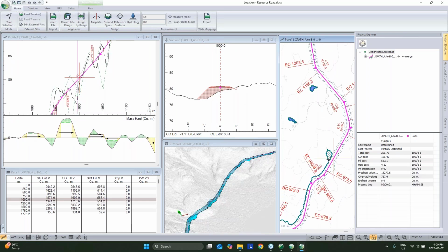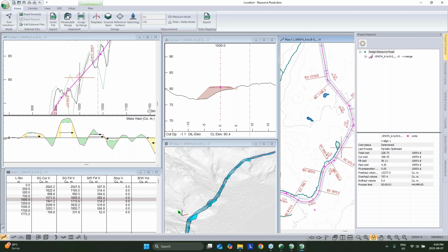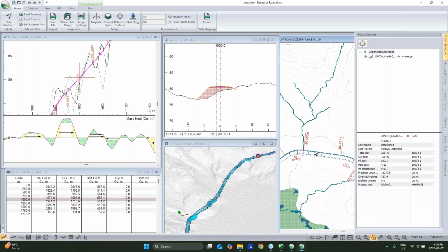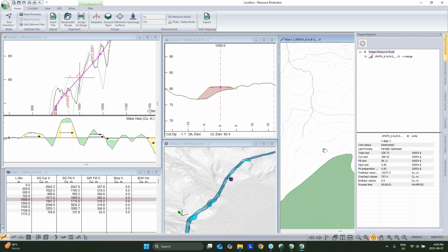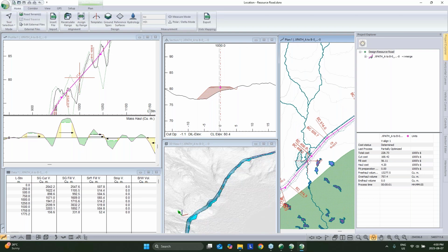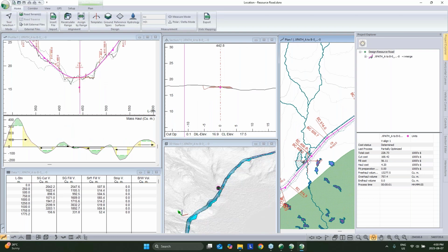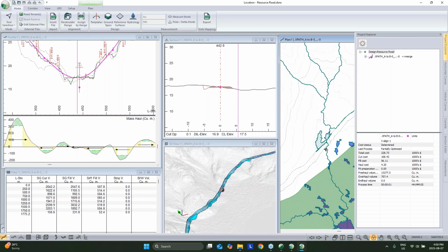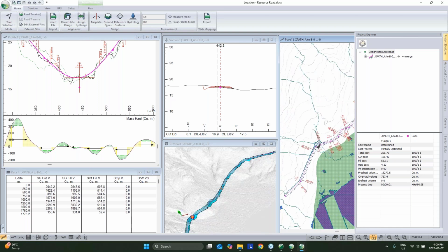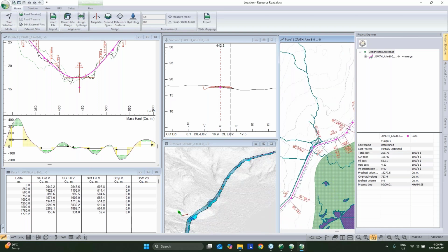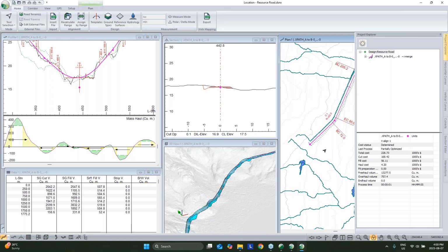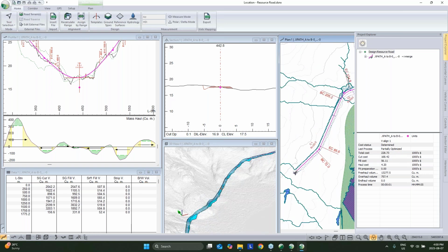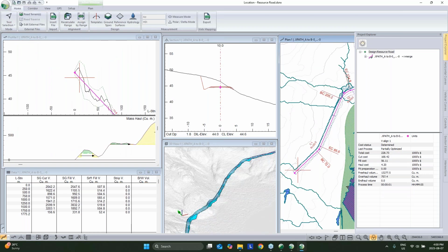We've got a really small catchment area, but we're creating ponding, and then that water would go back along our road all the way back to here, where eventually it flows over, and again, we've got our ponding. So again, I really like this just for that visual aid of running it before you've added your pipes, and you can see where you're intercepting things.